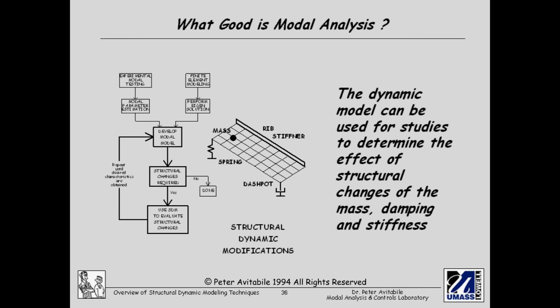So what good is modal analysis? Well, modal analysis is the process whereby we define the dynamic characteristics of the system. What we can use this data for is something called structural modifications. We could say, what would happen if I added a rib to the system? What would happen if I added a mass to the system? How does that change the frequencies and mode shapes? How does that change the response of the system? So that's a very, very useful tool when we're trying to understand how to modify a system.